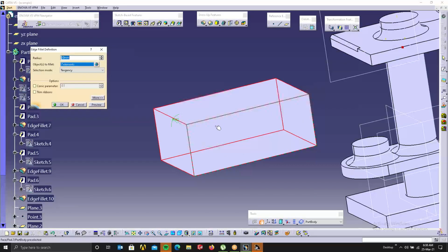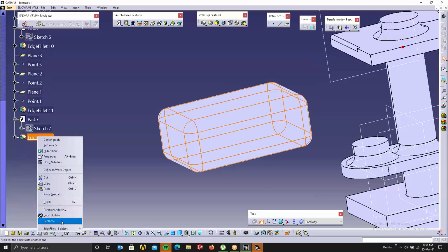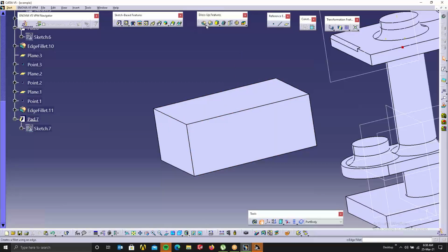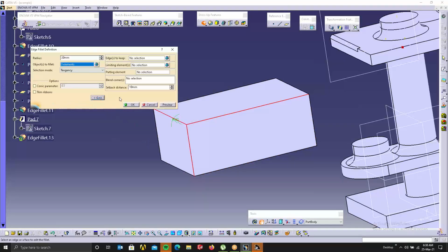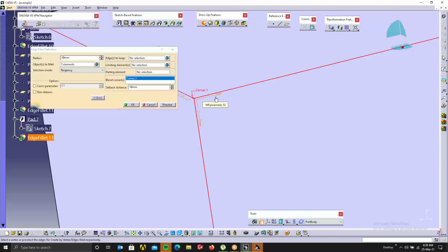Okay, so double click on this. I'll cancel this first. Yeah. So what I can do is delete this. To make it smoother, more even, I'll go here. I'll select 1, 2, and 3. I'll go here. I'll select the blend corner. Create by vertex, you select. Select this endpoint. Okay. We can see certain values are being shown here. 10, 10, 10. Okay, setback value.